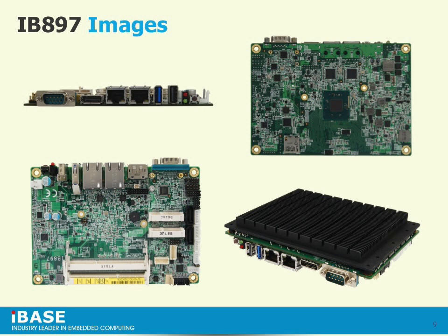So customers or users just put the SO-DIMM modules on board directly and can get dual channel performance. And from the upper right-hand side, you will observe that we designed our SoC to be located on the rear side of the board, and we also provide a heatsink, so the board can be operated as a fanless solution.